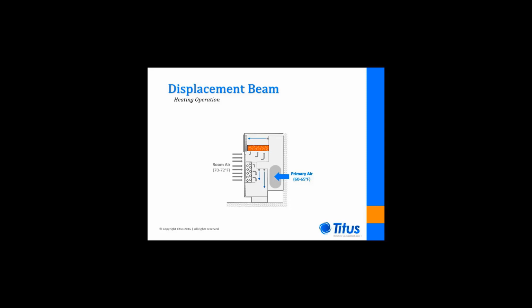Water flow to the upper heating coil warms the air induced into the upper portion of the unit. As its temperature is still slightly lower than the room, the primary room air mixture from the lower mixing plenum still discharges in a low-velocity displacement manner. The mixture of heated room air and primary air in the upper section is discharged vertically up the outer wall. The heating coil within the TOW units can supply limited, unoccupied heating even when the air handling unit remains off.